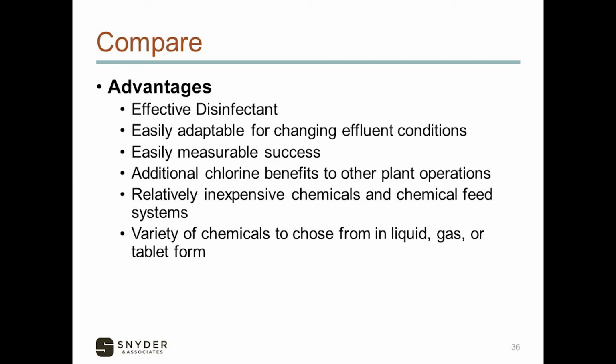It's a very effective disinfectant. It's easy to maintain, and most of us know how to do that because we do it on the water side as well. We could make a combined chlorine residual if we want. There's just a lot of advantages in that method. The availability of chemical system for other uses, such as we talked earlier, odor control, that's also a nice advantage if you already have chlorine on the site.